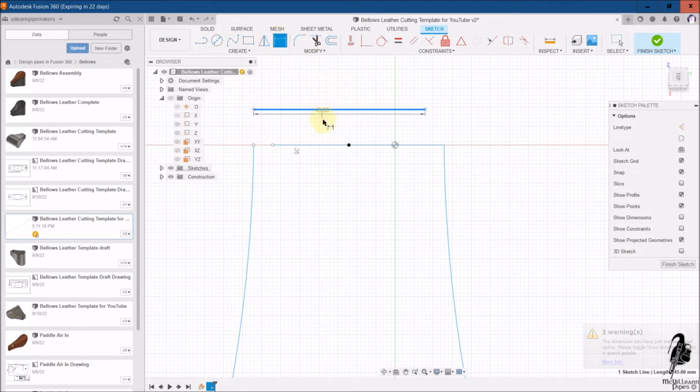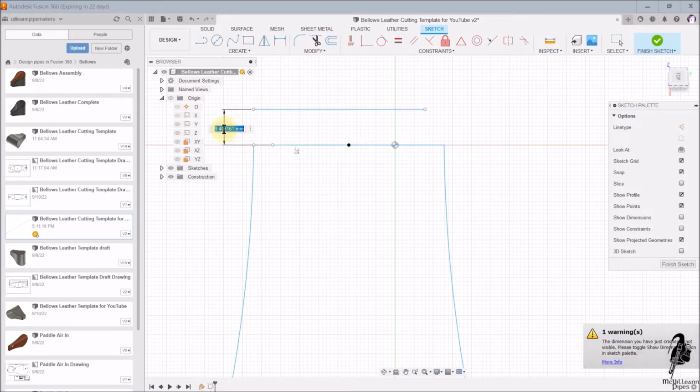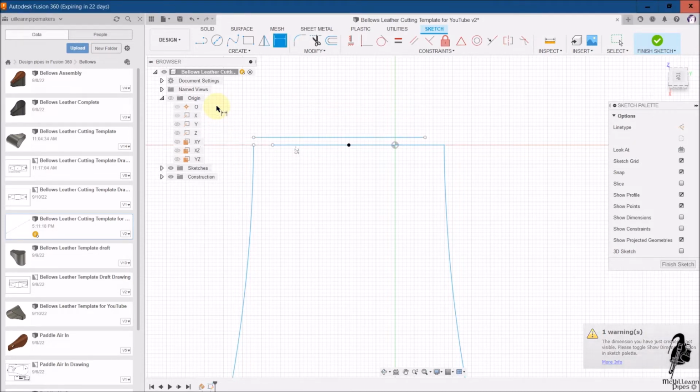Now we want to set the distance between those 2 lines. I'm going to pick 2 millimeters. Now the metal I'm going to use to build our flat pattern is steel, which has a thickness of 1.003 millimeters. So when I build that into a 1 millimeter thick plate and this one to a 1 millimeter thick plate, they won't conflict with one another. That would break the flat pattern.